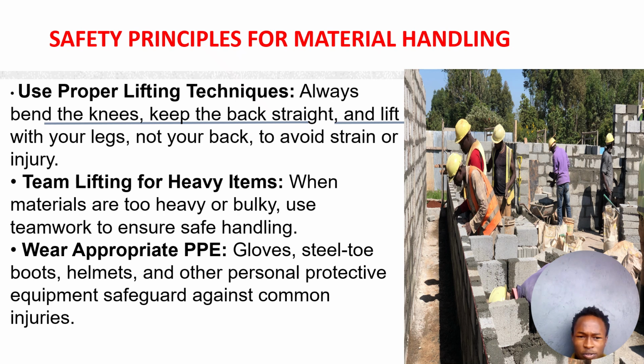Also, there is wearing of appropriate PPEs, that is personal protective equipment: gloves when touching cement, masks when dealing with cement, such that you don't inhale the cement, which is harmful to your health. Steel toe boots, that is safety boots, such that some of these materials don't fall and crush your toes and your feet. Also, there are helmets. Helmets should be compulsory on a site, because on a site, things are falling.